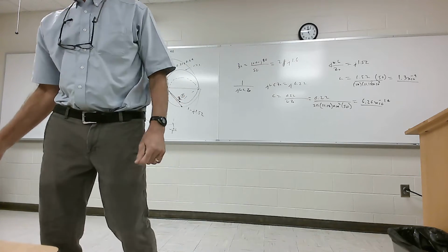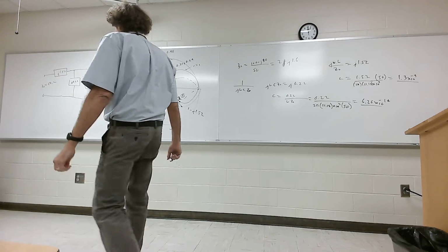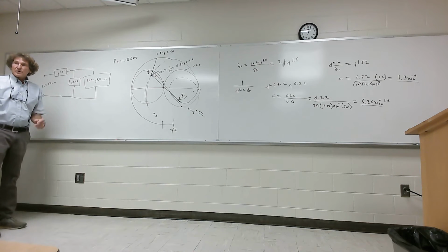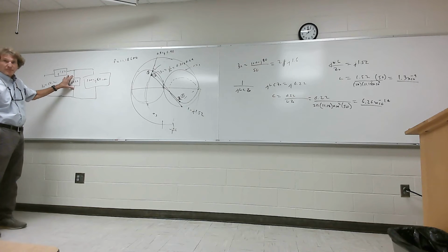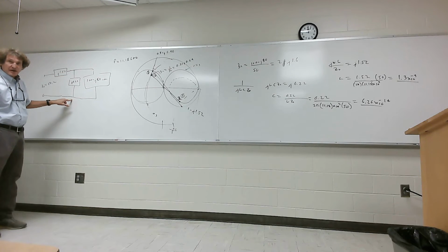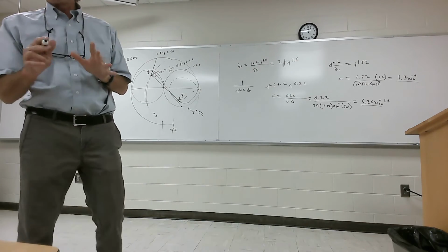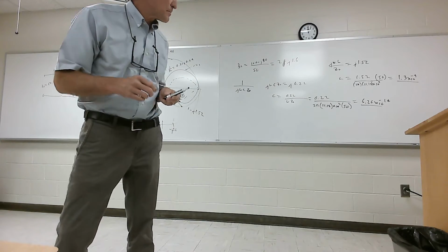How would you go about matching it? Really actually doing the matching, like something like that impedance? If an L section like this is too small, well, for this one, I'm going to tell you this much. When you're talking about a value that small, what you're probably going to do is actually just use a short stub to achieve that. Yeah, probably. It depends on the situation, but you have to realize that's very small. I mean, 10 to the minus 14.